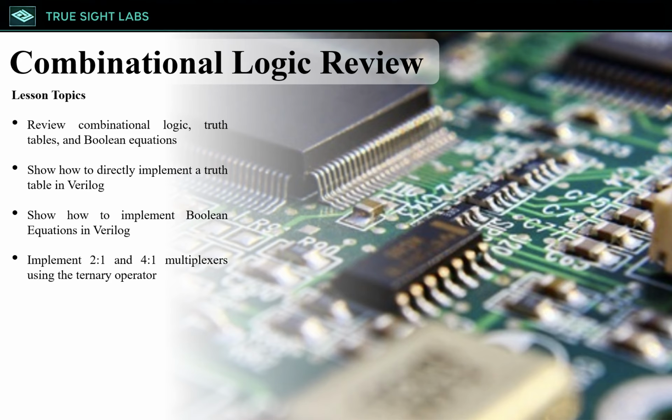In this course, we will start by reviewing the fundamentals of FPGA design. In this video, we will review combinational logic, we will go over truth tables, Boolean equations, and see how both can be implemented directly in Verilog. Finally, we will learn how to implement a 2-to-1 and 4-to-1 multiplexer using the ternary operator.